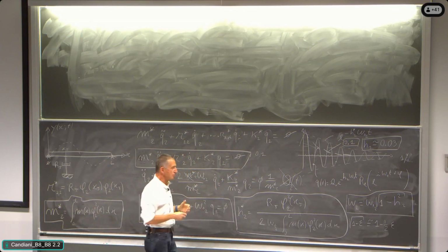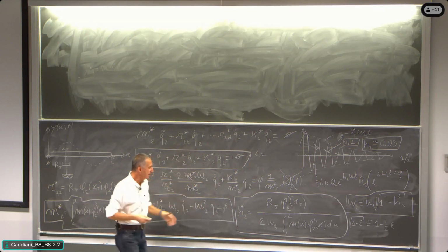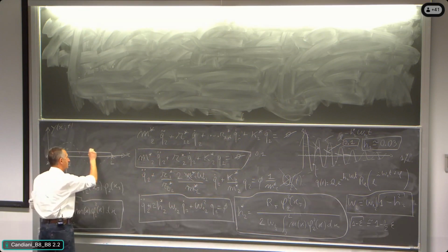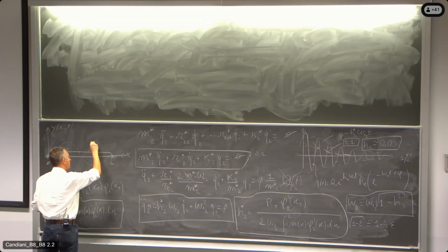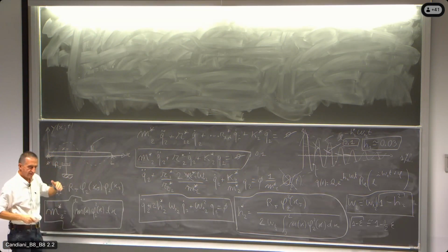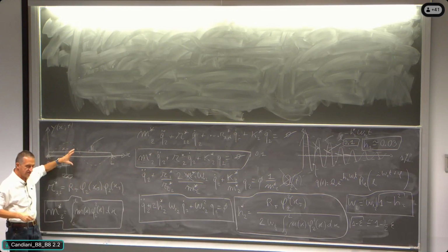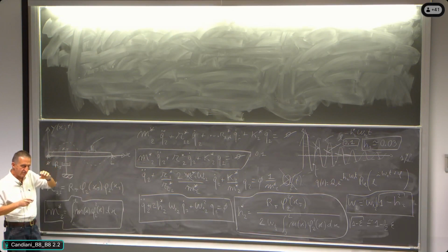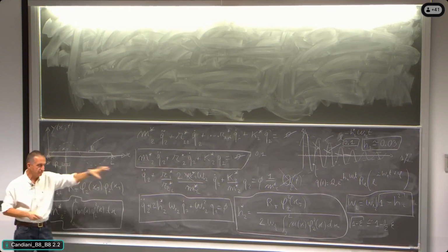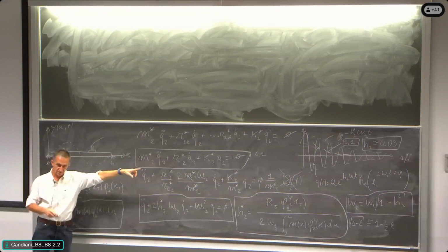If I am looking at the spectrum of the signal that I am reading here, so if I put an accelerometer here and I am reading, I will see the presence also of higher modes, although I am exciting the second. So I want to excite the second. I excite the second with the natural frequency of an exciter, with the frequency of an exciter that is increasing the amplitude of the second mode. Then I leave it to damp down in the way that we described here.